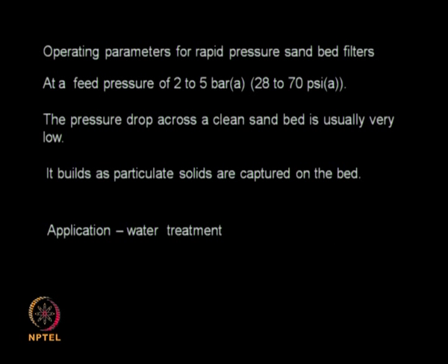So the operating parameters for rapid pressure filters: it can be operated at very low pressures, 2 to 5 bar maybe. Generally if the entire sand bed is very clean, the pressure drop also will be minimal, but over a period of time, if you are accumulating wasteful material, if there is going to be biological growth taking place, then slowly you may find that the pressure drop across these increases. So at those periods of time maybe you need to wash these type of sand filters. So as I said, they are extremely useful for water treatment type of application.